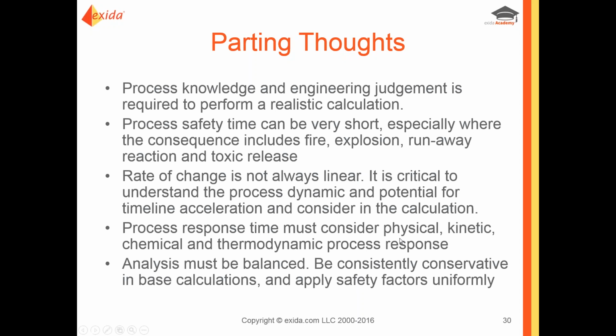I don't see any more questions up, but we had one question this morning. Does Excellentia calculate safety or SIF response time? And the answer to that question was no. It really does depend upon the process, so you need other tools that are looking at the process and that intimate knowledge of the process to really calculate that process safety time and thus back into your SIF response time.